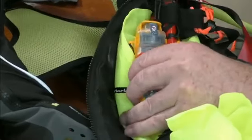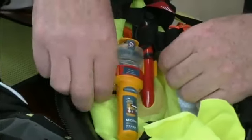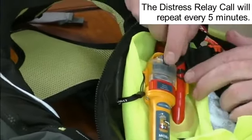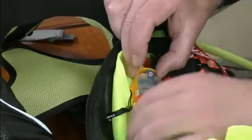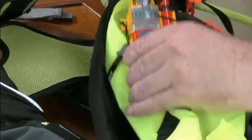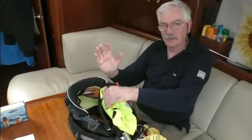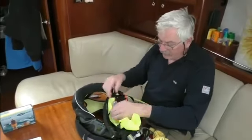So what's going to happen whenever this inflates, the bladder expands, the ribbon of course goes taut, it'll pop this arm cover off and pull that gray lever, at which time your antenna will deploy, and it'll be sticking up like this. Of course, whenever you're in the water, it should be perpendicular to the surface of the water. That's going to get you your best reception for your GPS. And that's all there is to it.